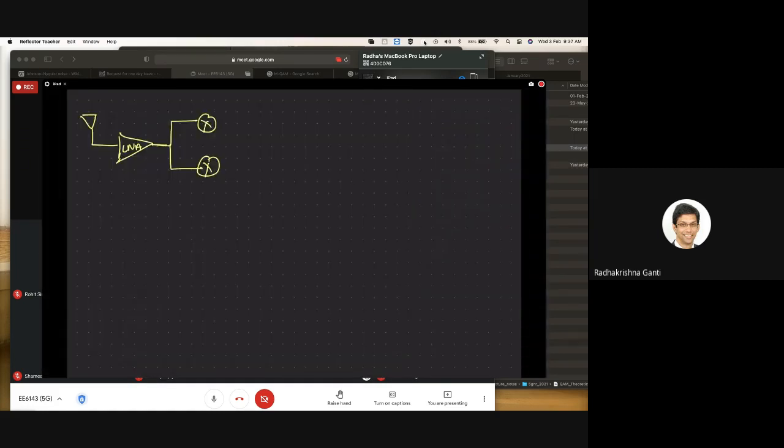So on the receiver side, what happens? You have the same oscillator that gets multiplied. There's a small low pass filter. You get your I, you get your Q. Then you do modulation, constellation demapping. So at this point, there will be an ADC, analog to digital converter.